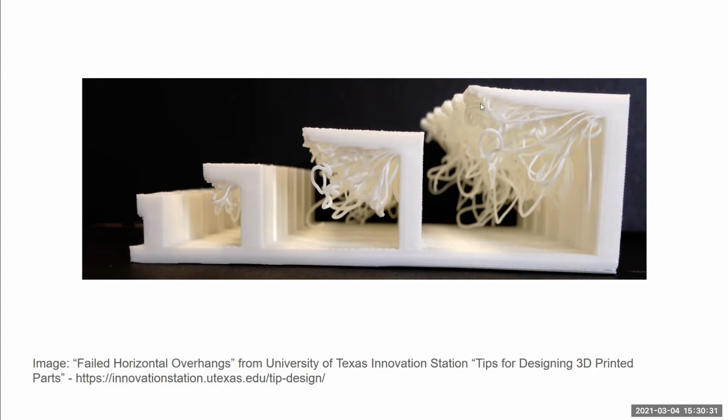Here, though, you see what happens when you have longer and longer overhangs. And this one on the far right shows a really good example of what this printer was doing: trying to print a straight arm out from around here, if you can see my mouse, around the corner, the armpit of that little overhang.